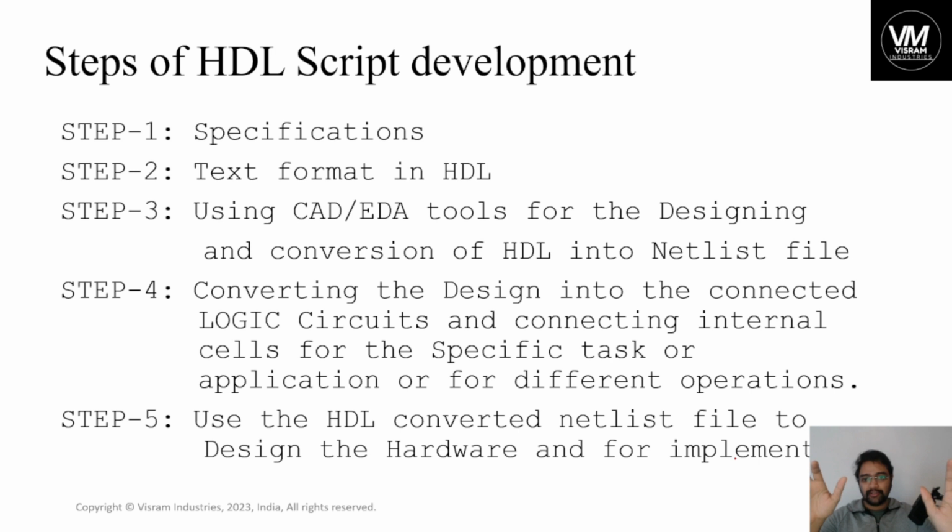Okay, very good. But what type of wires should be connected between this OR gate and the next neighboring element? It might be an AND, flip-flop or mux, anything. That kind of clarity is handled in place and route. Okay, this OR gate is very near to the input A, so the input ports and this OR gate should be very near.